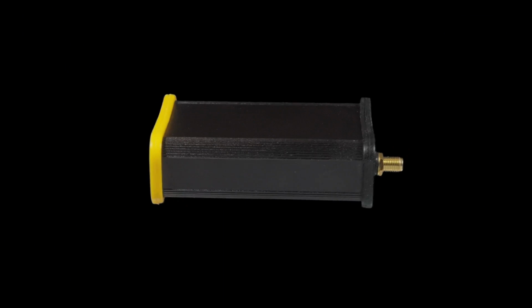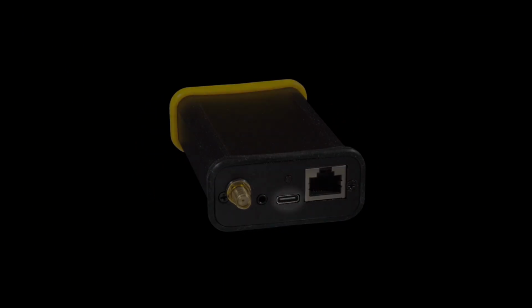Moving on to the other side of the device, first obvious thing is the USB-C port in the center, not much to say about that. It's a USB 2.0 full-speed device, and we try our best to meet the USB specs. I think the only thing we don't really support is suspend mode, where we should technically drop power usage to very low levels, and we just don't.